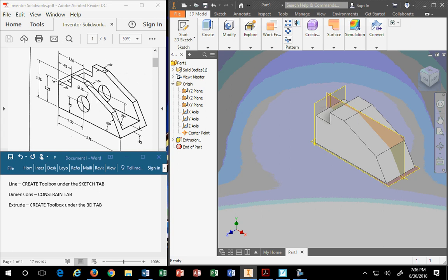one of the things we realize is that the walls of this object, the exterior walls, are common all around. They're 1/4 inch. So now I'm going to teach you a new command called shell. Not the gas company. It's a command called shell. Now think of what shell is, like an egg shell. What do we know about eggs? They're hollow on the inside. They got stuff on the inside. So they have a thin wall to them, right? So the shell command is about making something with thin walls. Or it doesn't have to be under a particular thickness. It's just that's the word, the analogy.